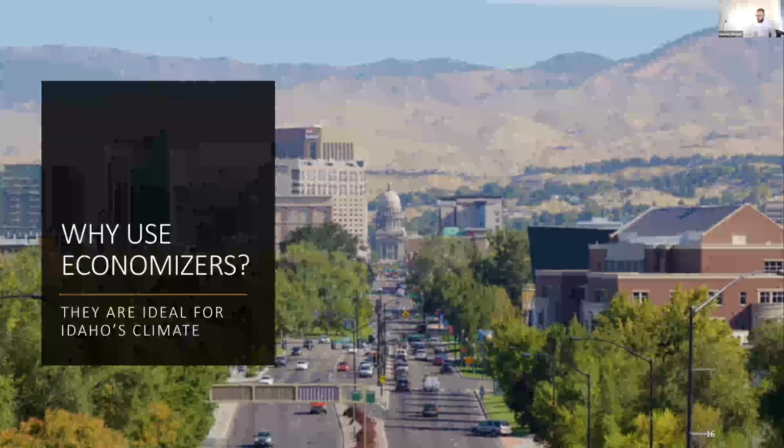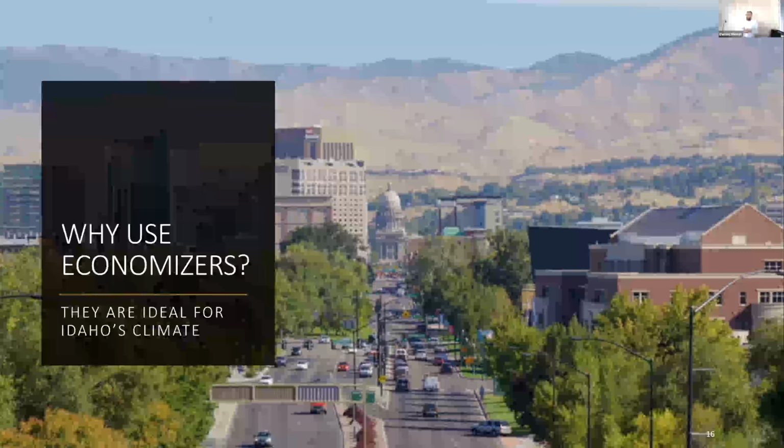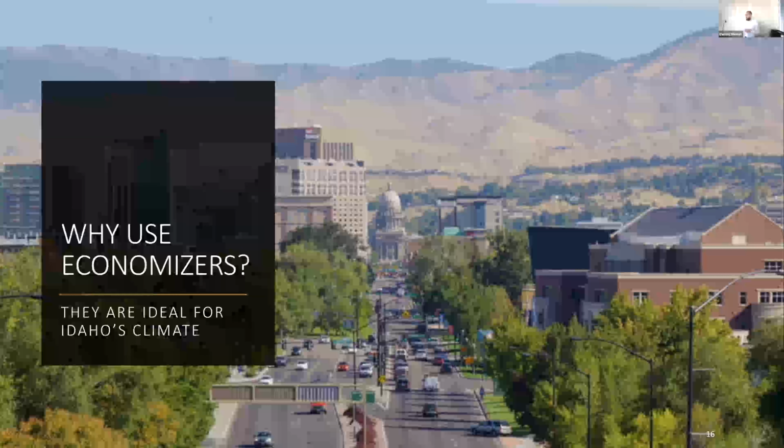One project that our lab did, a number of years ago, was we built an energy model as a digital twin of a Moscow campus building. It was a classroom, a pretty large building that shall remain nameless for reasons you'll understand shortly. But we realized that they never had their economizer going. They had one installed, the controls were there, but it was completely locked out. It would never actually bring in that cool morning air.